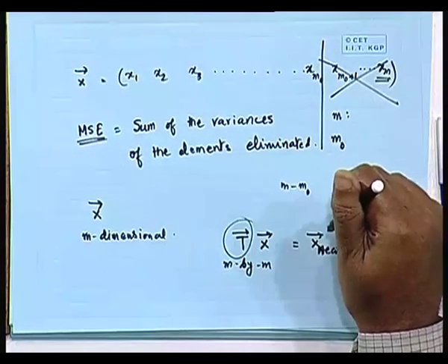The difficulty is that, instead of designing it based on a fixed kernel, we can design our own kernel and try to find the optimal kernel or the optimal transformation, so that in the transformed vector x nu it is possible to find an optimal transformation T such that if we eliminate the last few points, we will be eliminating the terms with very low variance, and eliminating terms with very low variance will lead to lower mean square error. So we should be able to use those kinds of transforms in an optimal sense. That is exactly what we are attempting to do.